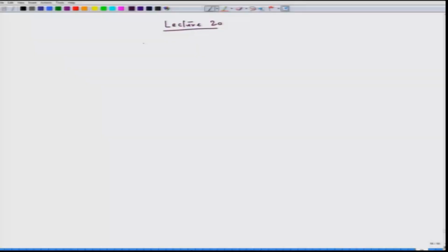We have already started looking at the Pourbaix diagram because it is an important feature in electrochemistry, and when you look at corrosion, this understanding of the Pourbaix diagram is very, very essential. Now, as we have said, the Pourbaix diagram is nothing but a stability plot of different phases in the plot of E versus pH. This is the Pourbaix diagram. This is basically a stability diagram.